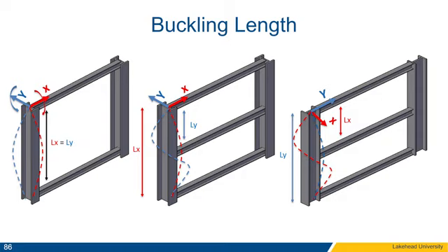And also we talked about what type of beams will be limiting the buckling lengths. So we mentioned that whenever the beams are oriented in the X direction, they are limiting the buckling length in the opposite direction. So for example, if the beams are oriented with the x-axis, they will be shortening the buckling length in the y-axis and vice versa. So it is exactly the case in the second example here.